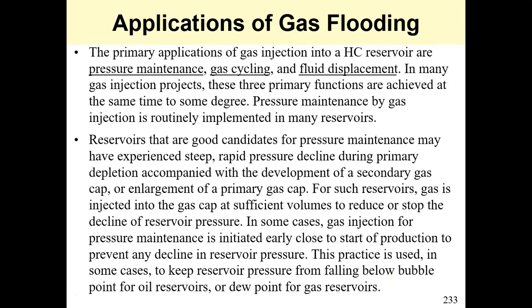So let's look at applications of gas flooding. The primary applications of gas injection into the hydrocarbon reservoir are pressure maintenance, gas cycling, and fluid displacement. In many gas injection projects, there are three primary functions.